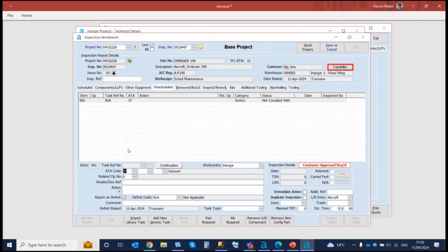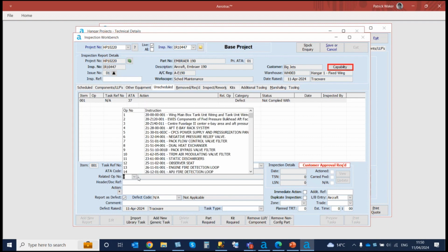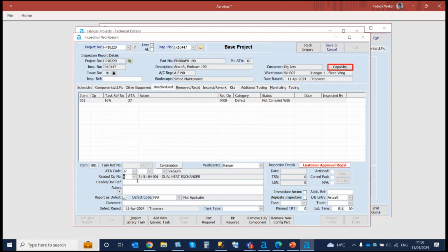Something like that. Whatever. What's my ARP number? That one there. And so again, we found a defect. And as part of the inspection of the heat exchanger, we found a filter clogged. Checked. Fan and shaft is making metal. So comment is remove shaft.